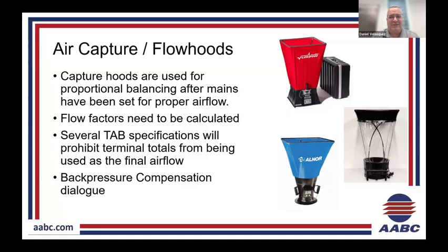In the bigger projects, especially the senior techs, if you get into big TAB projects and they've got the 230594 specification sections, they will prohibit in TAB reports that the hood airflows are the summation of the air handling totals. It may be in a different kind of note in the spec, but it'll always say summation of outlets does not mean the total airflow. That's where the duct traverses come in. Do a nice duct traverse on your unit. That's your total airflow. You do your statics,